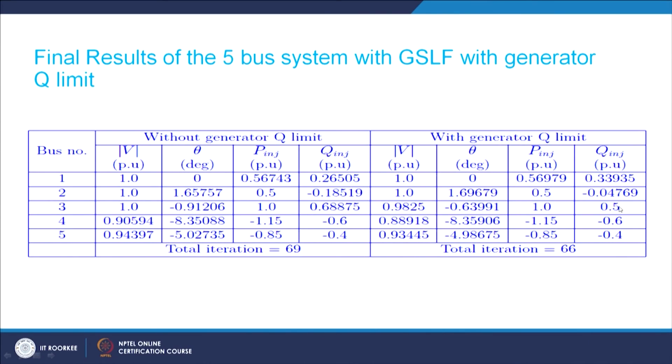Same thing also here. Here our total amount of reactive power load, effective load, is coming out to be something like 100.4 MVAr, but the total generation by the generators is only 83. So, the rest, that is 17 to 18 MVAr of reactive power, is being generated by the shunt charging susceptances of the lines.